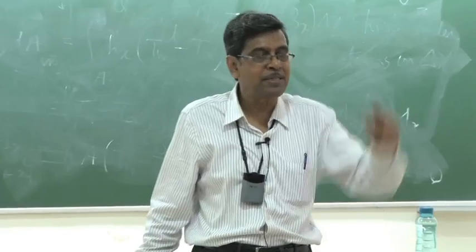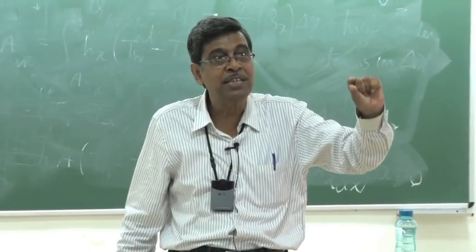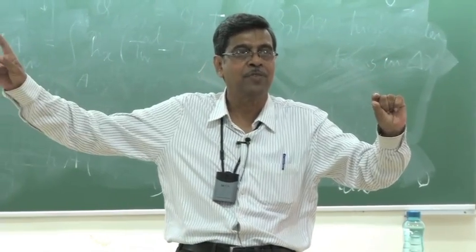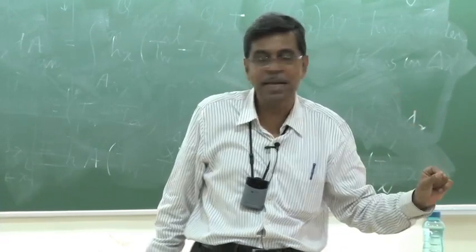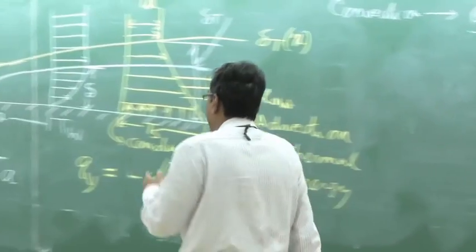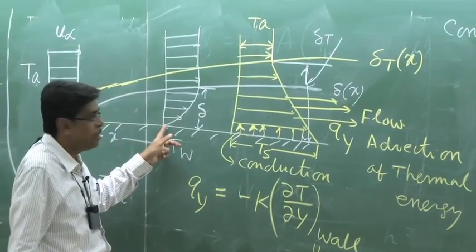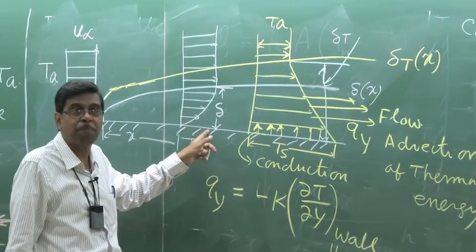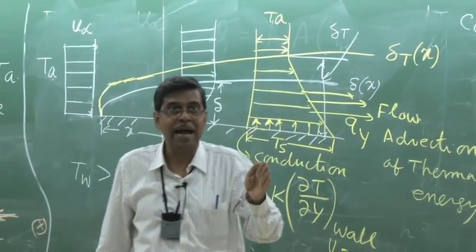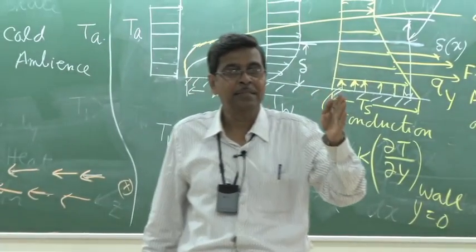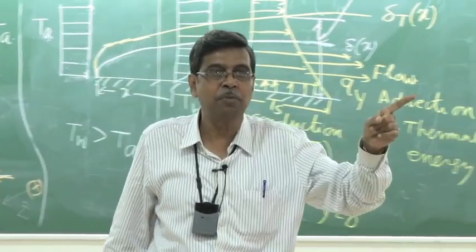So therefore what happens? The thermal boundary layer goes thinner and thinner. Nevertheless, it becomes 0, like the hydrodynamic boundary layer. So there is a no slip condition at the surface with respect to velocity, that means it is 0 because the plate is at rest, and a no slip condition at the surface as far as temperature is concerned. That means the surface temperature has to be maintained.